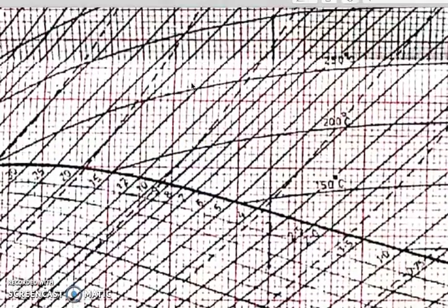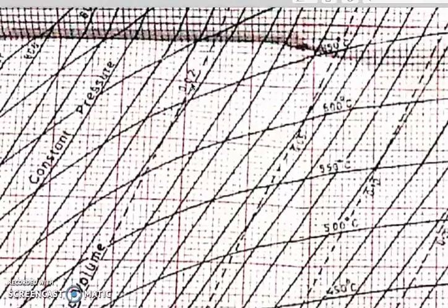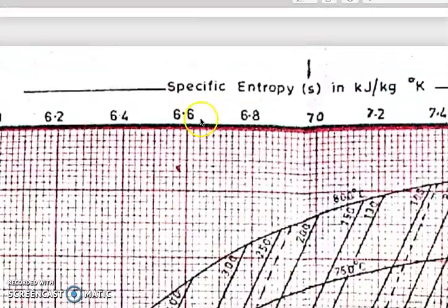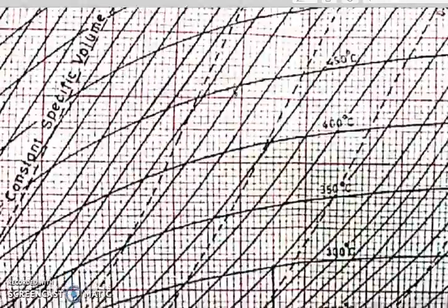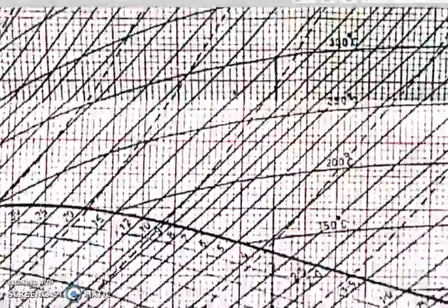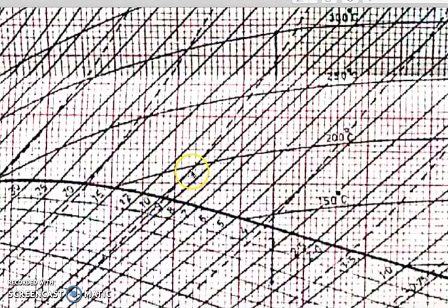So we can easily see the condition, and for reading the enthalpy we will move horizontally towards the left vertical axis, and we will read the enthalpy there. For the entropy we will move straight to the vertical axis, and then we can read the entropy from here, fine. Now what else we can read from here is the specific volume. This was 10 bar and this was 200. Specific volume can be read between this line and this line.